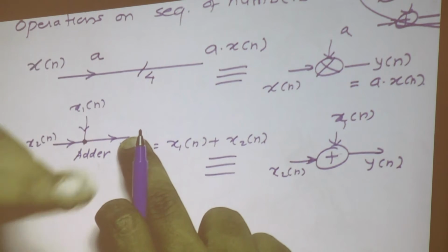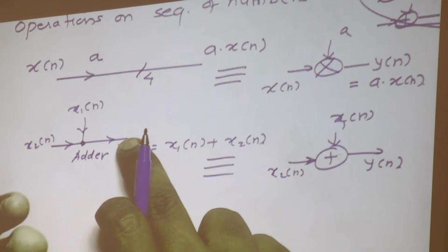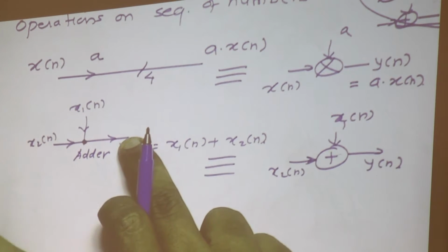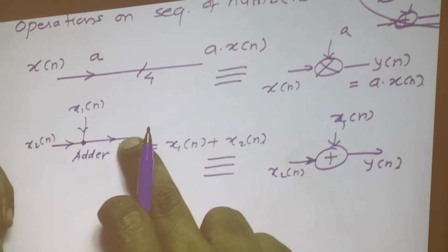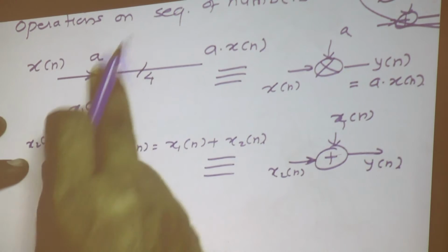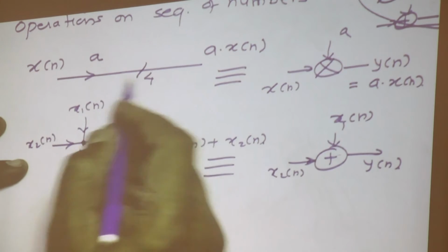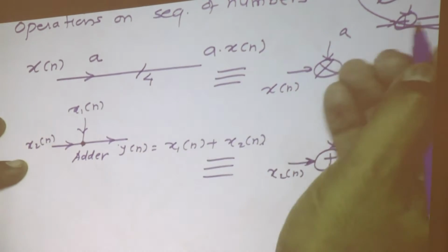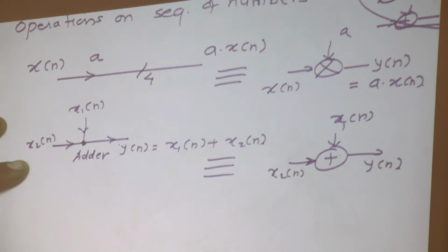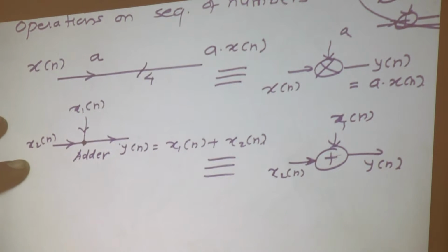So, you need to curtail, you need to cut the 2n minus 1 bit number into an n-bit number, to quantize it into an n-bit number. There is a numerical inaccuracy. We are adding an error here. If I represent this as a number of 2n minus 1 bits, then somewhere else you get a multiplier which is 2n minus 1 and an n, which becomes 3n minus 1 and so on. So it would be infinitely growing. The word length required for consecutive multipliers will grow.